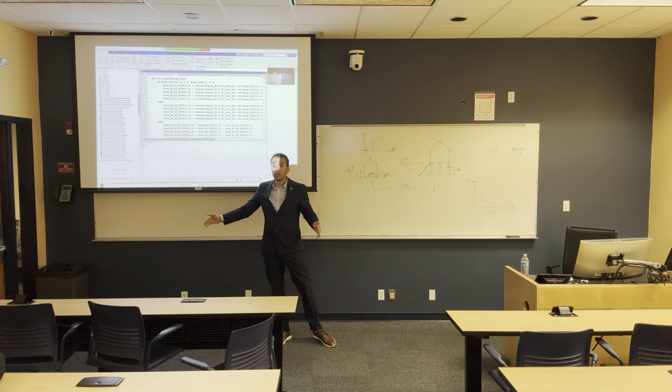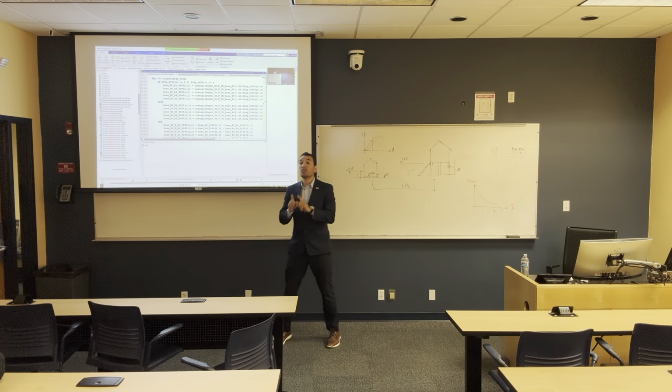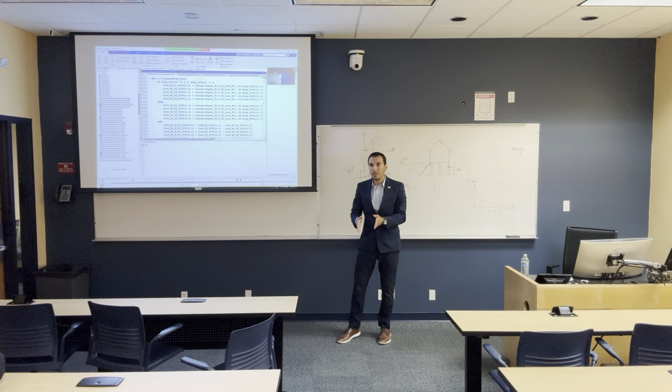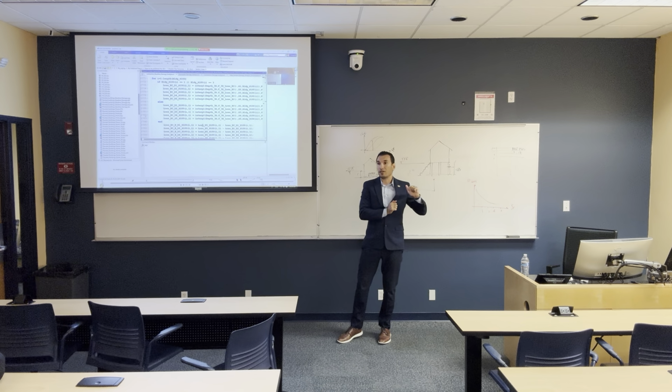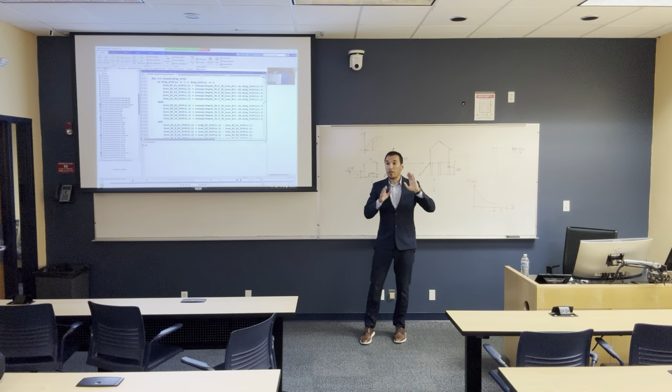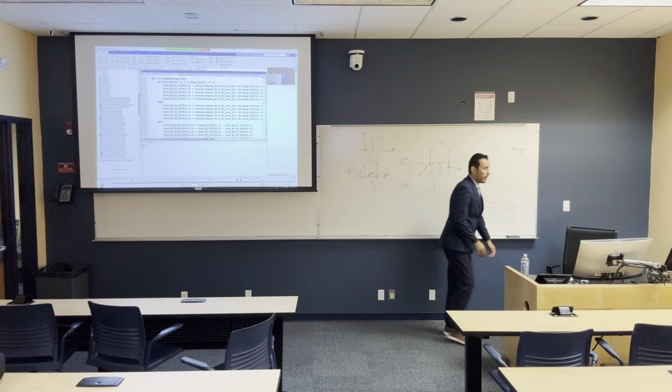So 3 mitigation measures, not scenarios, because each measure has multiple scenarios. When we did barrier, we did scenarios where the barrier is 20 centimeters, 40 centimeters, 60 centimeters. Pumping, 1 day, 2 days, 5 days. These are the scenarios. But the measure itself is the pump, or the measure itself is the flood barrier.